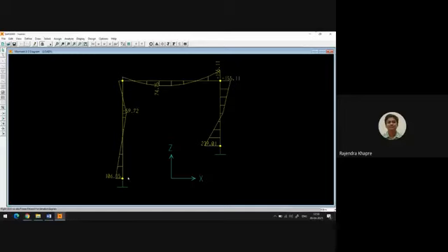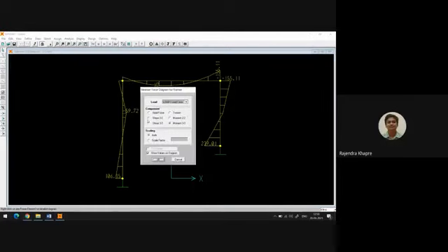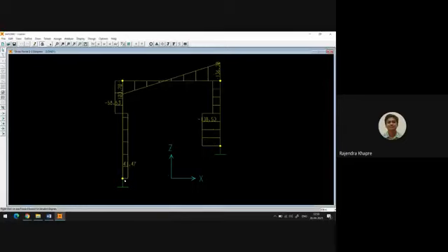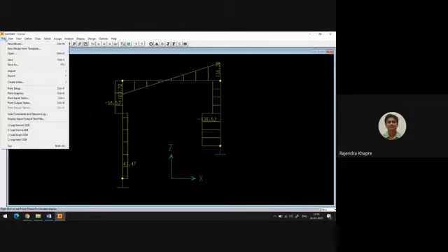This value, if you refer to the notes, is 106, and this value is also 155, and this value is also 239. Okay. So this is about the bending moment. Also, this is the shear force diagram. So if you want to have the shear force diagram, you select this F, and you can say shear 22. Okay. So once you select this, you will find there is a shear force diagram displayed on the screen.